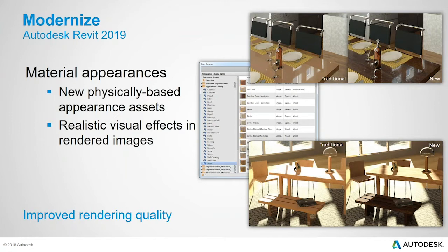One of the things you may notice when you're taking an older Revit project and migrating it into Revit 2019 and you pull up your material appearance asset browser, is that there are little icons of the assets that have an orange triangle in the bottom left-hand corner. That basically is a visual cue to tell you that that asset is a legacy asset that's being brought over or migrated into Revit 2019. You can take these legacy assets and modify them so they can take advantage of the new functionality within the materials appearance as well as the ray tracing.